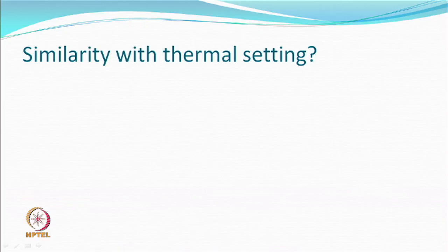So, it will again go between the molecules, break the crystallites, and obviously partial, because we do not want to lose the fiber itself. So, this is the similarity that we have discussed with the thermal setting. Okay. So, partial melting, recrystallization, relaxation of molecules to the best energetically favorable configuration. So, you do heating, cooling, here you have solvent uptake and solvent removal.